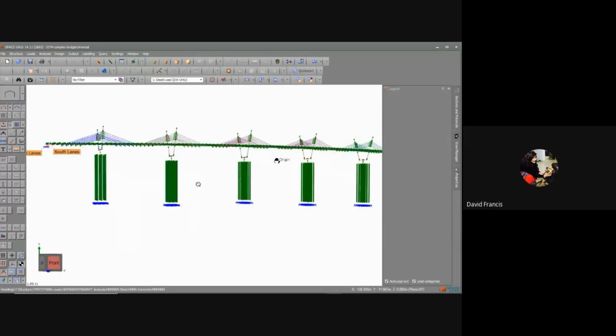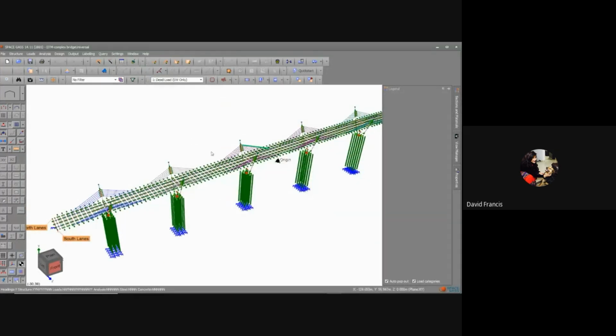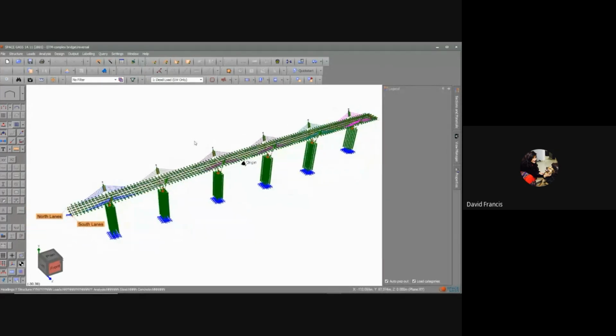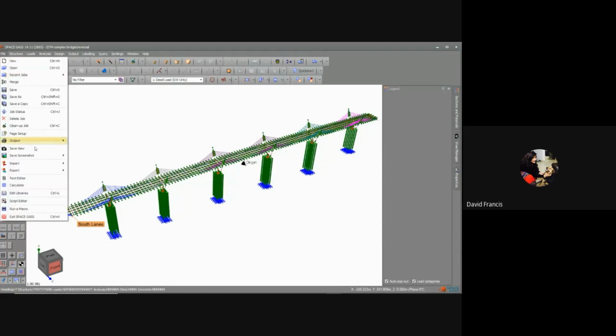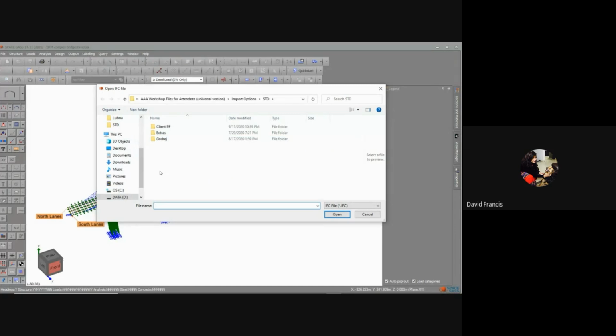All right, this bridge is a real bridge, and the actual physical structure was generated from the wizard in Midas, and we imported it. So getting back to the import tools, we imported that using IFC4. There are some problems with Midas's IFC4 file, so we have our own import options. If we go to file import, I'm not doing IFC today, but IFC step, you'll go and select